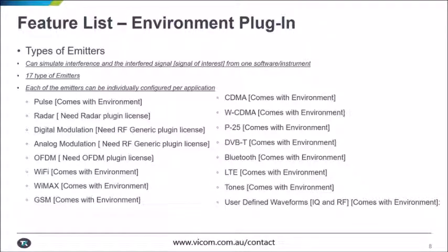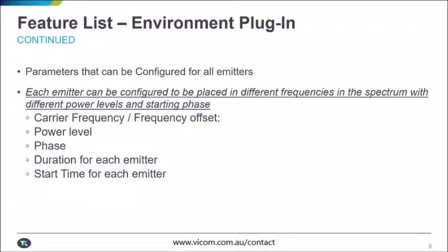You can also capture your own signals and use the user-defined waveform capability that allows you to also use scenarios with these specific captured type signals that can be captured with a spectrum analyzer and then used with the environment plugin. So with this particular tool, you can change the carrier frequency offset on the fly, power level, phase, duration of each emitter, and start time for each emitter.